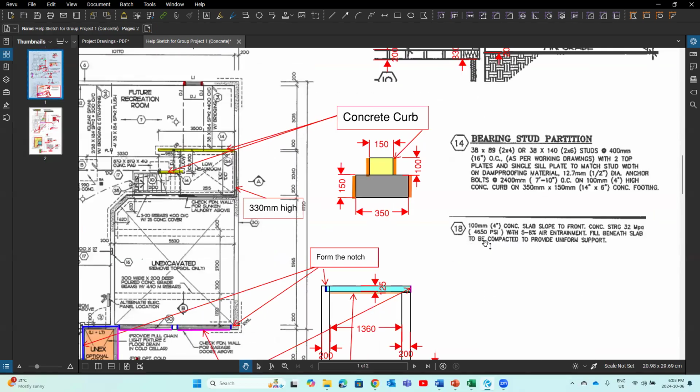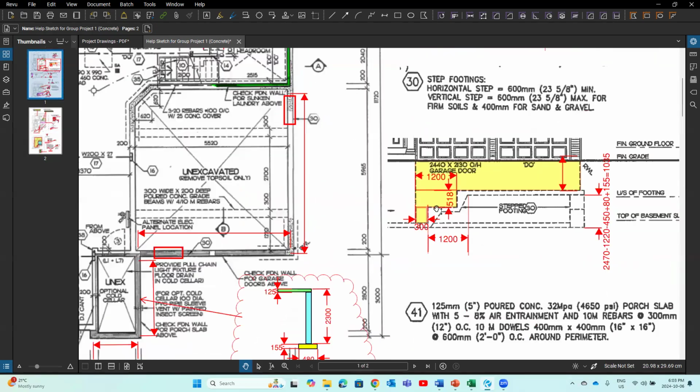For foundation wall, right? Concrete, you still consider the extra here, right? You have the area here, you multiply by thickness, you get a volume, right? Think about both sides for the foundation wall. Understand? That's concrete. Say formwork, both sides, concrete. You need just take the length multiplied by thickness multiplied by height, or take the area multiplied by the thickness. I would get my volume, right? Understand that, right? Okay, that's this part.